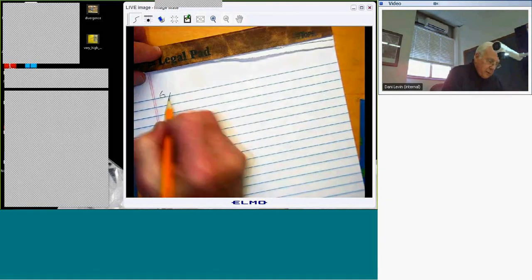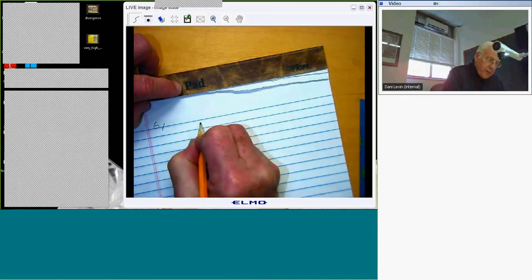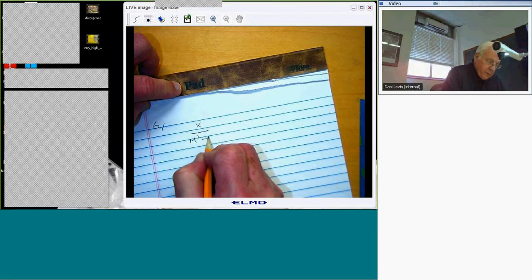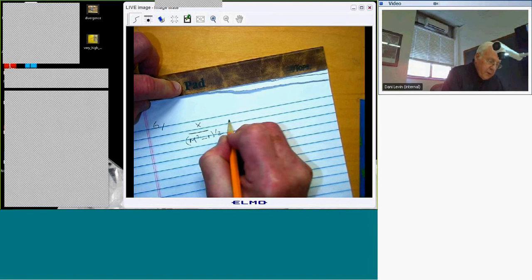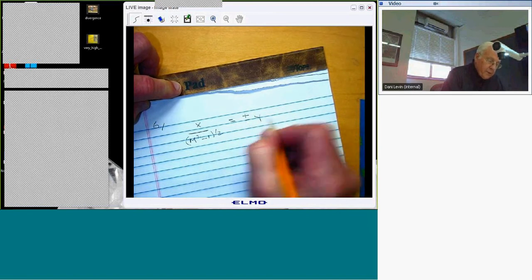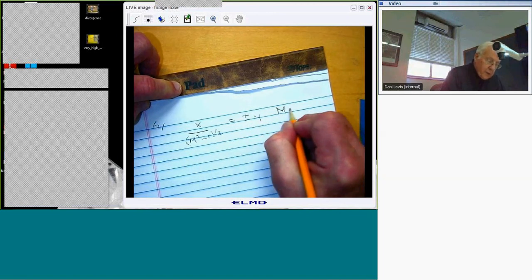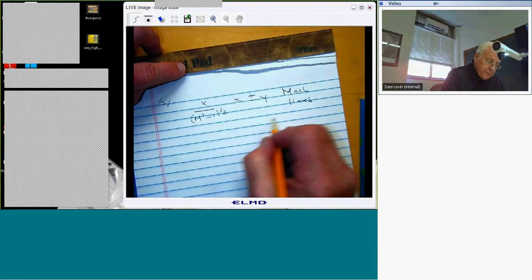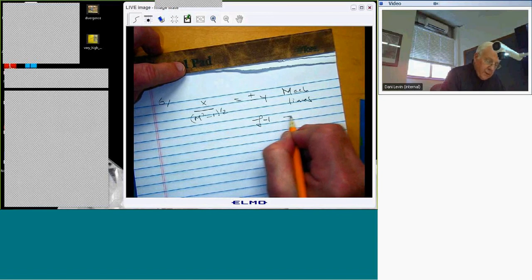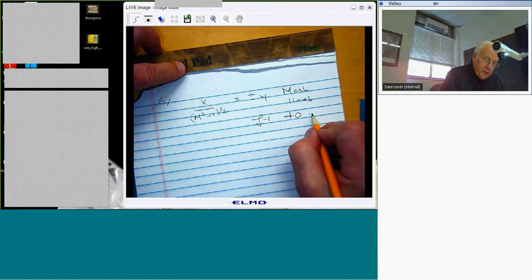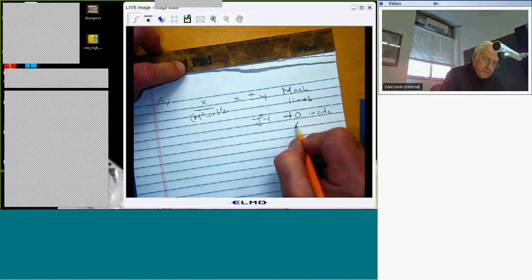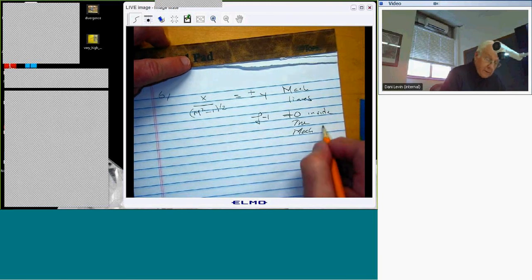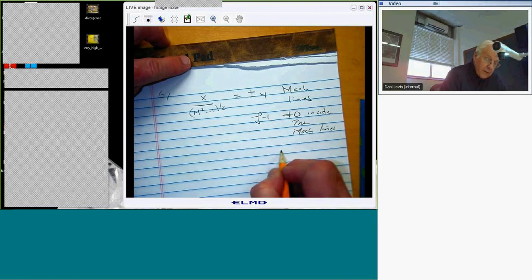First of all, these wonderful lines are x over the square root of M squared minus 1 equals plus or minus y. These are the so-called Mach lines. And this inverse is not 0 inside the Mach lines, and it's 0 outside the Mach lines.